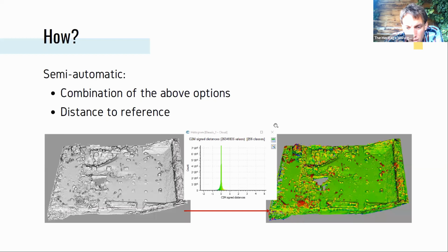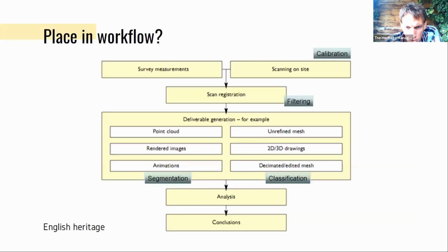Actually, I use this method quite often in an iterative approach. So if I have a plane, I try to fit a best fitting plane on a raw point cloud. I say, okay, I have 1 meter above, 1 meter below. I remove these points, I make a new plane, remove 50 centimeters, 25 centimeters, 10 centimeters. So you can apply it in an iterative fashion to increase the quality of your point cloud by doing that.